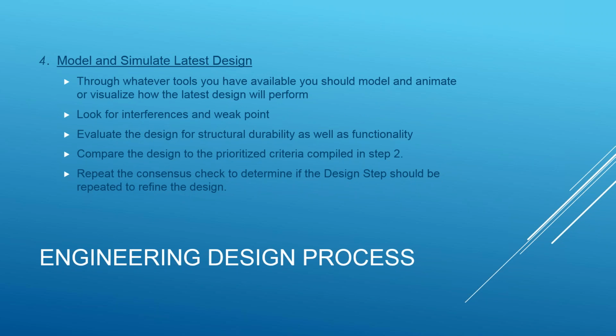Okay, the next step would be to model and simulate your latest design. You can use whatever tools are available to you to model and visualize how that design will perform. You might want to make a model. You might be able to do that with one of the CAD programs where you can animate the robot. You want to look for interferences and weak points.